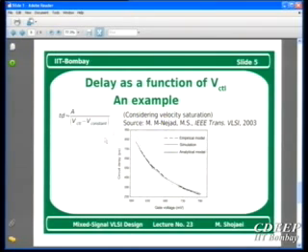But fortunately for the case of PLL, you want a linear relationship with frequency, which you will get. Therefore, for DLL design, we usually use some particular range. But for PLL design, you can use the entire range. That is also an interesting result. And interestingly, they have shown that this analytical model and simulation are almost matching.